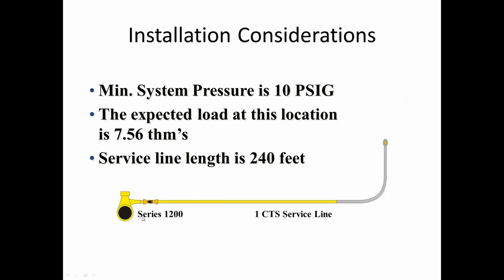As you can imagine, if your service line is set and sized correctly to protect the entire service line should it be open to atmosphere, you can expect that if you open that valve to atmosphere it's going to do just that. It's going to trip the excess flow valve, and you'll see that by a sudden reduction in the flow of gas, because essentially you've opened that valve to atmosphere and simulated a breach, although it was at the stop valve.